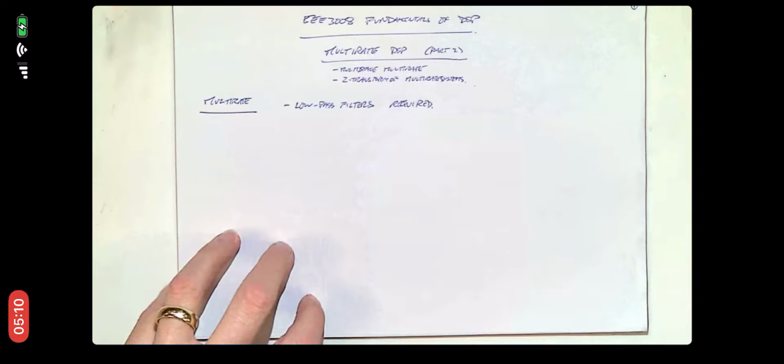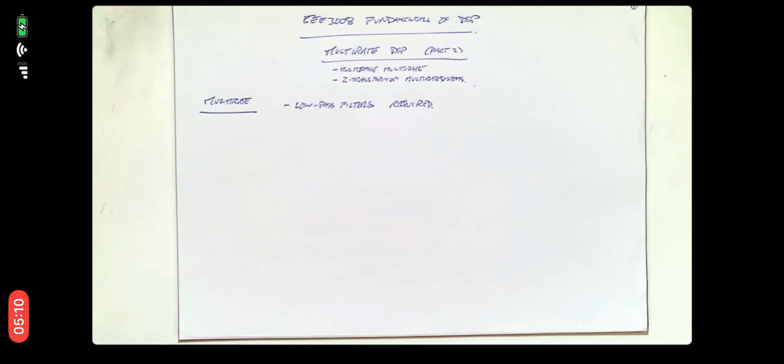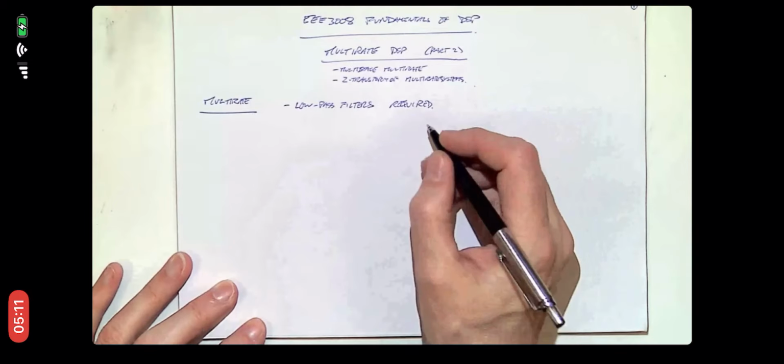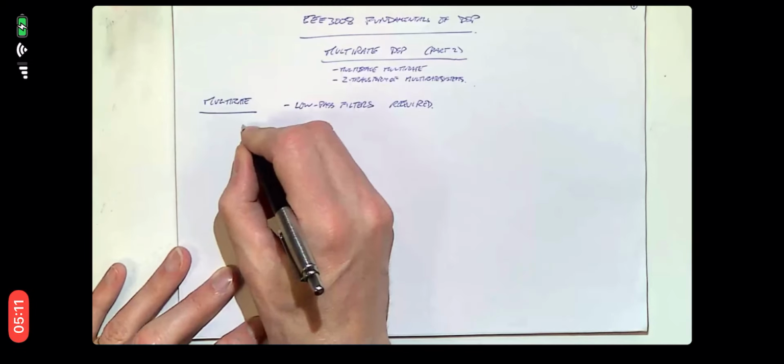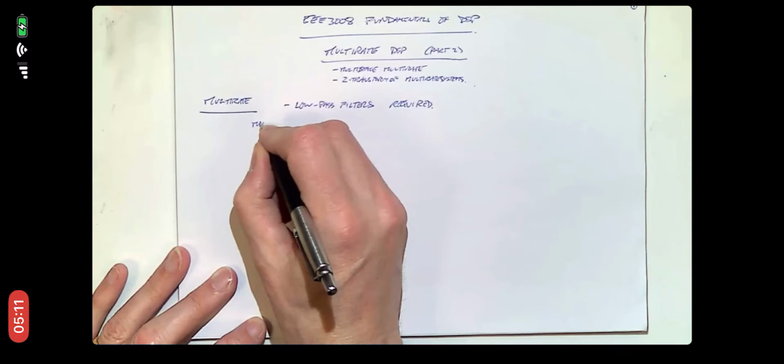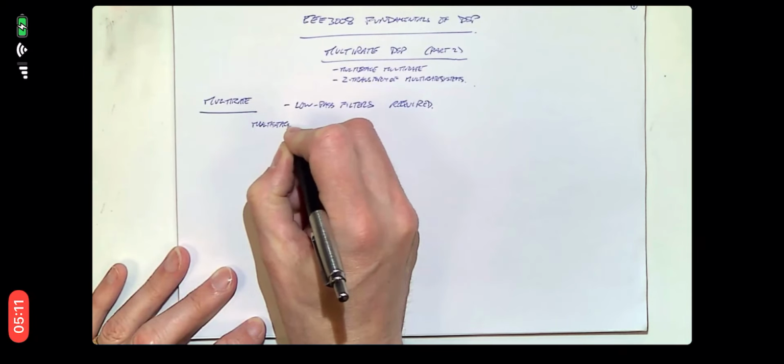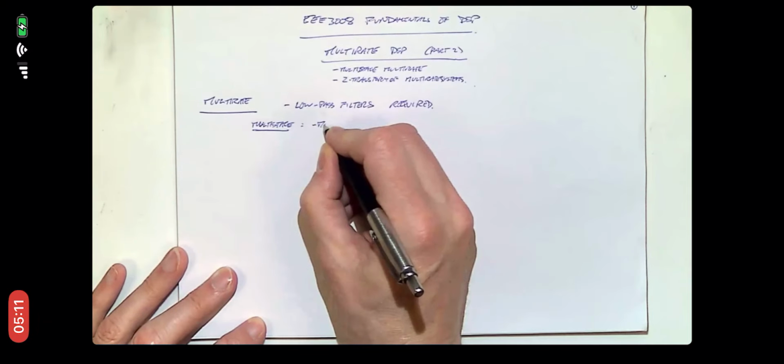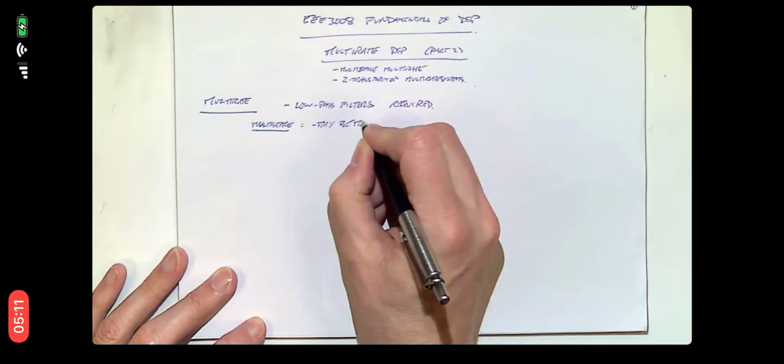Required. So if we're downsampling, we have the low-pass filter first and then do the downsampling. If we're upsampling, we have to do zero stuffing or interpolation, and then use an interpolation filter, which is a low-pass filter. So we've got two different places where we might use the low-pass filter. Now, the key point of the multi-stage version is that it may be more efficient